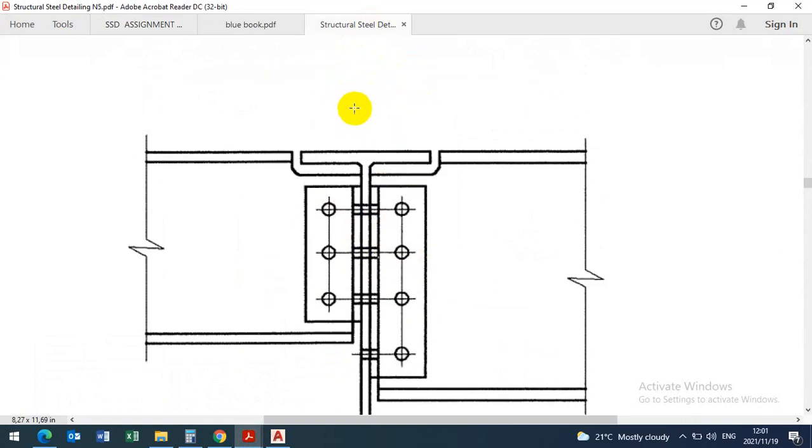When you're looking from the top view here, you won't see these holes that are cutting through the web of beam 1. They will be in hidden details. Even if you use a plate here, or you use the angle cleat. They are using the angle cleat, so it means the angle cleat will be hidden details as well. If you decide to use the plate, this thickness from here to here is going to be 10, a plate that will be welded on the web of beam number 3. But we don't need the detail of the plate.